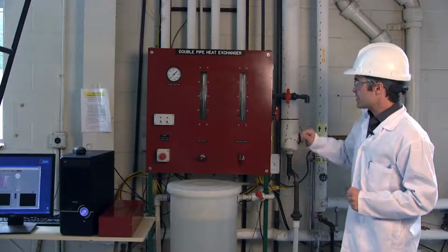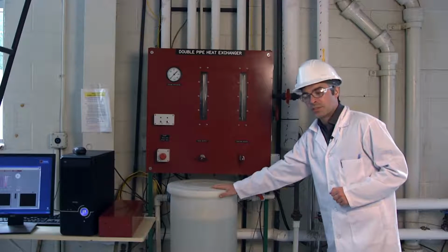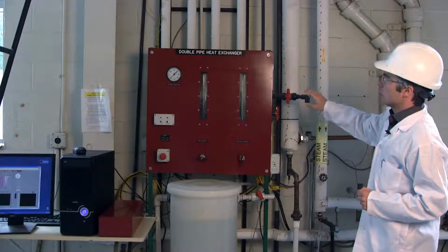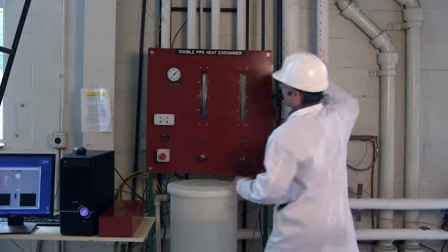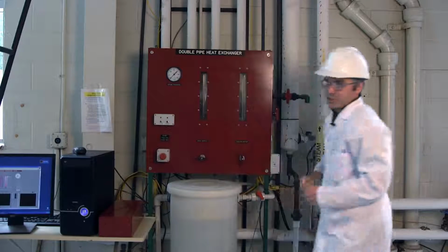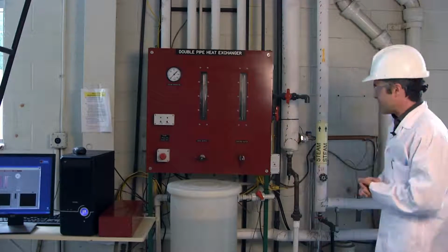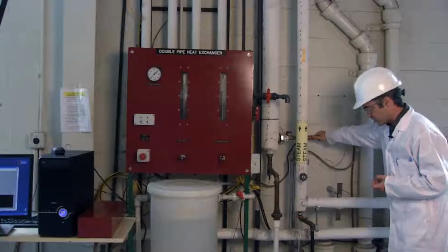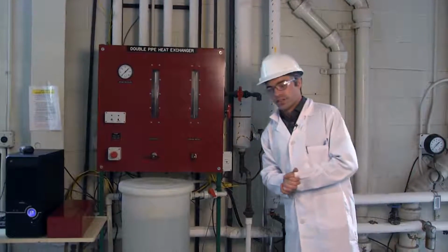So, this laboratory will draw, as mentioned, water from this reservoir. This must always be maintained full of water. In order to turn on the cooling water for the entire system, which is the first thing that you should turn on, the switch is located well into the back and will usually be turned on by the TA prior to your arrival. If you can hear the water flowing, and you will see at the end of the steam unit, the cooling will always be draining into the drain. This is how you know the cooling water is on.